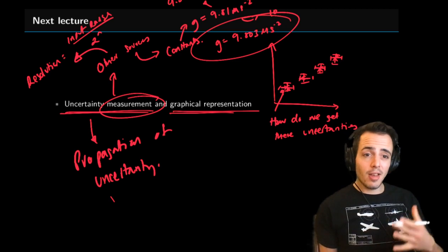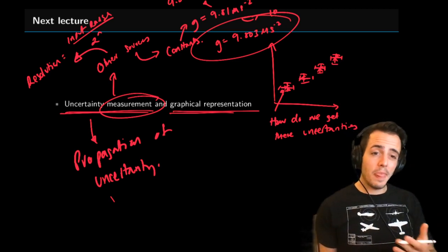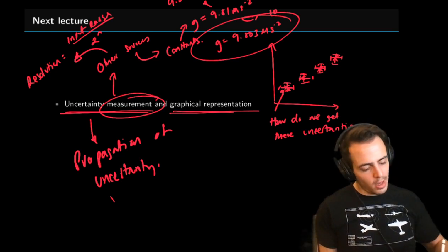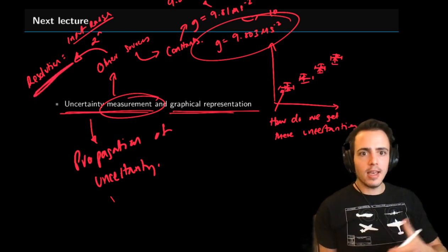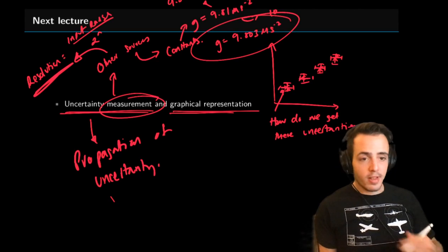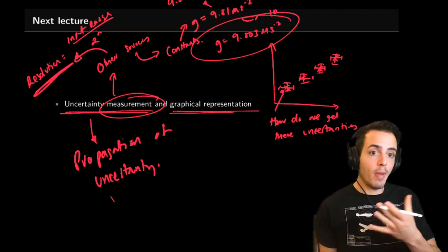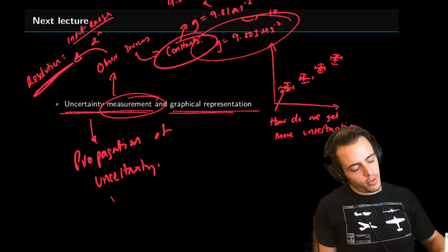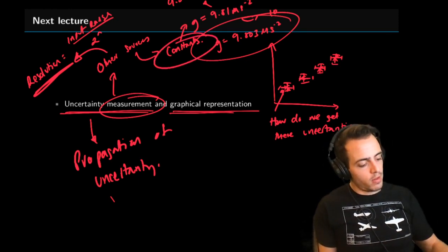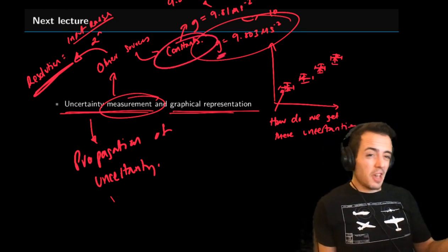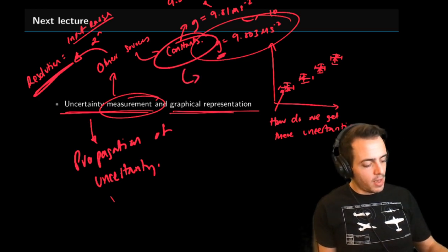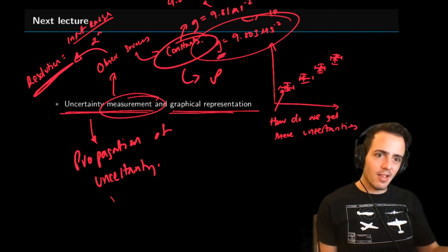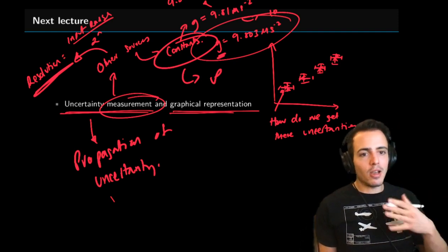So we're looking not just at how, if we took some measurements, how good was our transducer at measuring those raw things themselves. We're looking at how good was our ADC, what was the resolution of them. If we were measuring pressure but we're then converting it to velocity, what constants do we use to get from those? One of them would be gravity and part of the calibration perhaps. Another one would be, say, the density. If we're measuring a density, how precisely do we know that? And then we look at the uncertainty there.